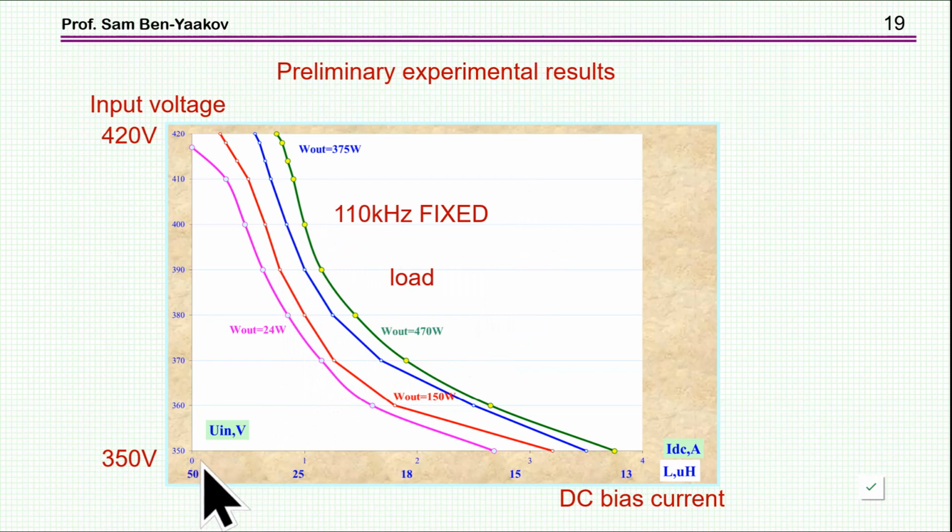And here we see the change in the inductance between 50 and 13 microhenry. It's much less than what I've shown earlier; no need for such a large change. And we see that by changing the inductance, we can accommodate all these changes. The current that is needed in this particular embodiment is up to, say, 3.5 to 4 amp. Remember that this current goes to a DC winding, which has resistance of just copper and very low voltage, because the DC resistance of the copper will be low, depending on the cross-section of the wire that we choose. In any event, this will incur low power dissipation.